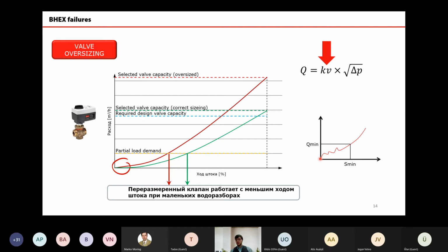My average temperature of the heat exchanger is dropping to the cold water temperature. That means during one tapping, which is classically like, let's say, showering, it can be 2-3 minutes, sometimes longer. We easily can see that the average temperature of the heat exchanger is changing from approximately 100 to 20 degrees, so delta T 80 degrees, close to 15 times.